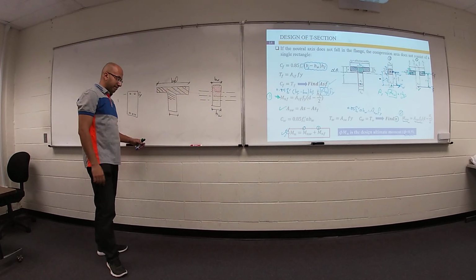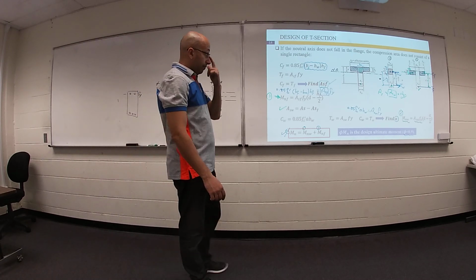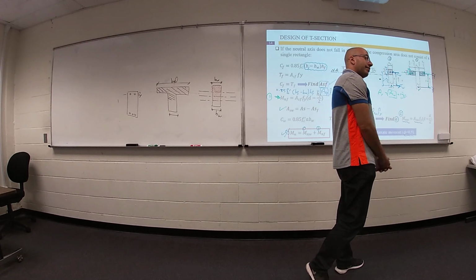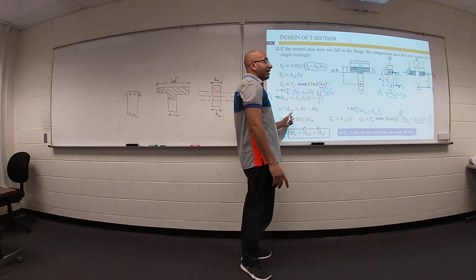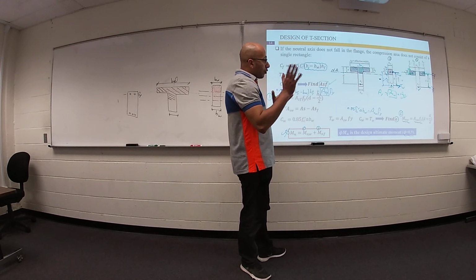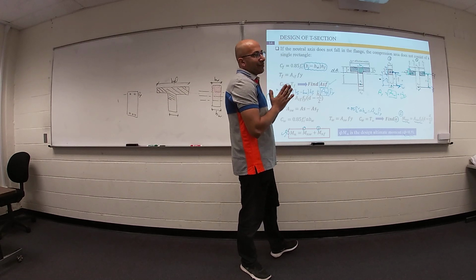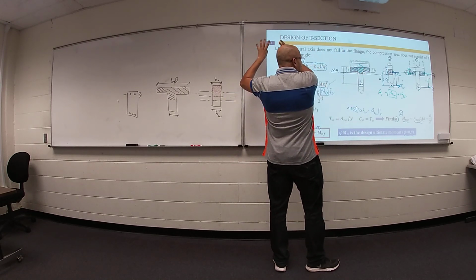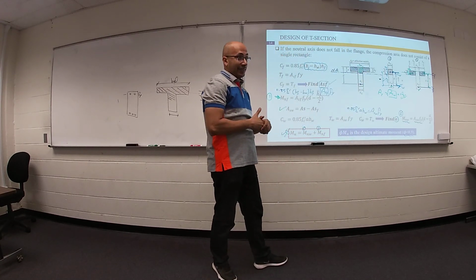I have one more question. When we do our initial test to determine that the neutral axis is outside of the flange, isn't that the same a, or do we have to solve for a different a? Yeah, we will get another a. Your first value of a is not correct 100% because it was based on an assumption, and this assumption is not correct.